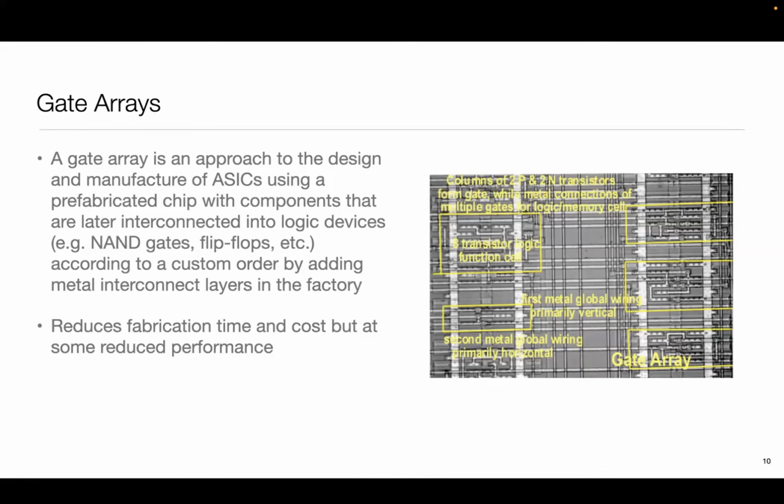So there are many, historically. One is something called gate arrays. Actually, stepping back, one is that I do everything from scratch. I just draw transistors on silicon, literally, right? Everything is under my control. That's the extreme case, but that really requires a lot of expertise. And even in software, we don't do that, right? We make use of building blocks provided by other people, and then we make our software on top of those libraries. So a gate array is an example of that.